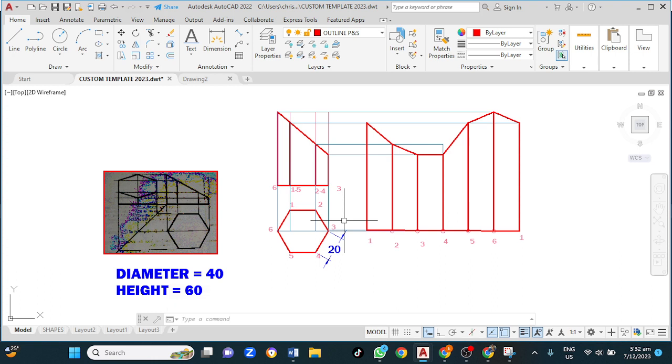Please note that this shape is based on where we cut the figure. Wherever we open the figure is referred to as number 1. So I label this number 1. It means that the figure was cut here at number 1. And this is the pattern that we need to create in order to draw the development for that. Yes, so there we go. We have just drawn the development for a truncated cylindrical hexagon.